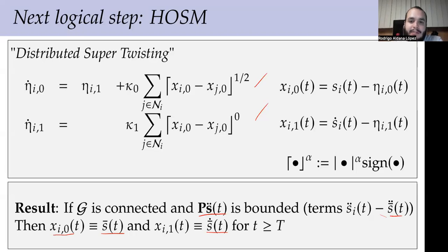So if the question was whether the Lyapunov function constructed from the Lyapunov function for differentiators works, that particular case doesn't seem to work. Even for the super-twisting, you mean? Yeah, even in this case, if you have a network of two nodes, just two nodes, the same Lyapunov function works.